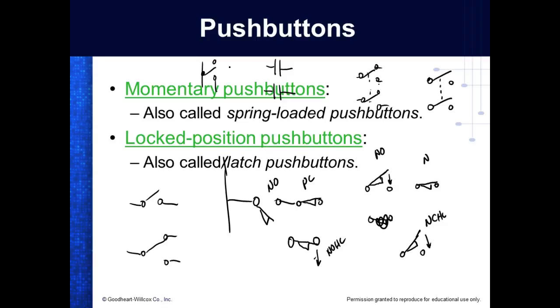This is the push button station. The two push buttons on the right that are labeled stop and start. The one labeled start is a single pole, single throw, normally closed. The one labeled reverse is a double pole, single throw, normally closed. It depends on which way you hook it up.